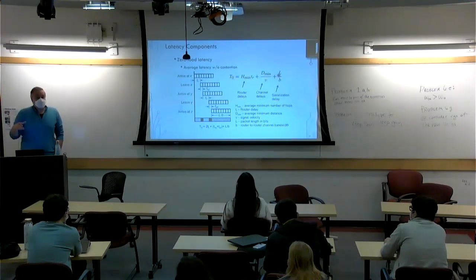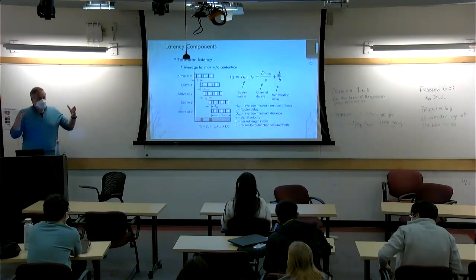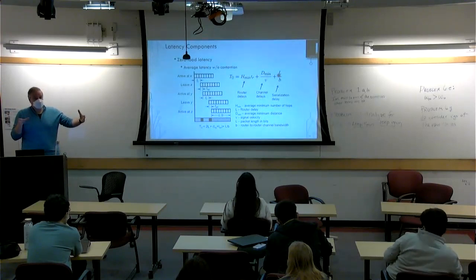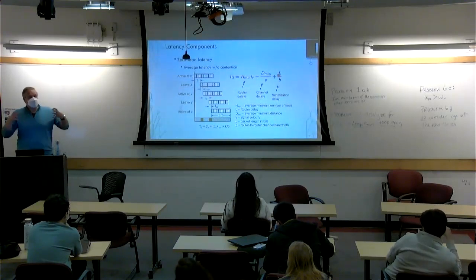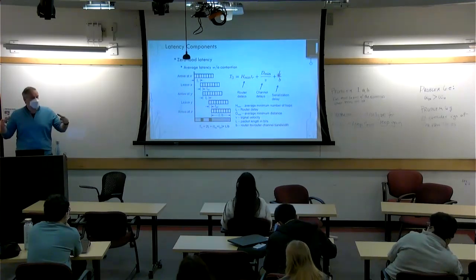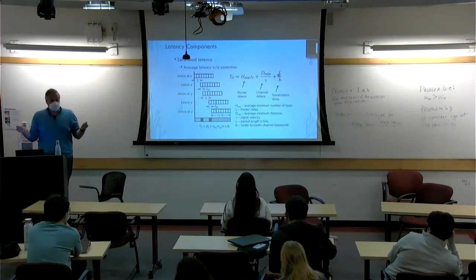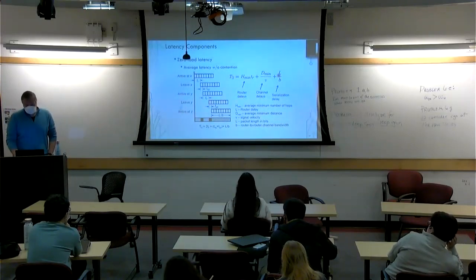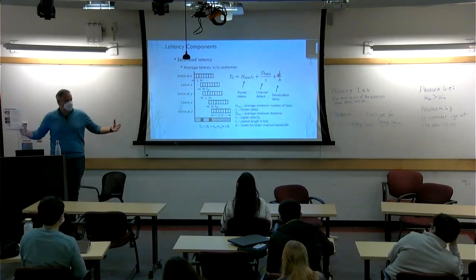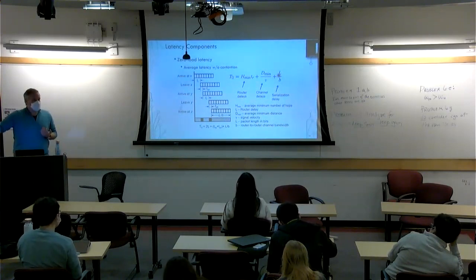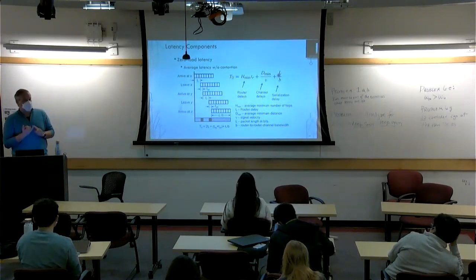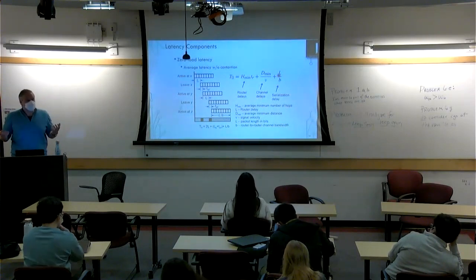You will eventually have to pay that serialization delay somewhere, depending on what size of message you're using. Somewhere you're going to have to assemble the whole message, and only when you assemble it are you able to use it. That's where you pay the whole serialization delay. That's why it's nice to have very big channel bandwidth, very big router bandwidth, so you can just instantly slurp all that up. But that unfortunately costs you power and costs you area: a lot of wires, a lot of repeaters, a lot of flops. So that's unpleasant.